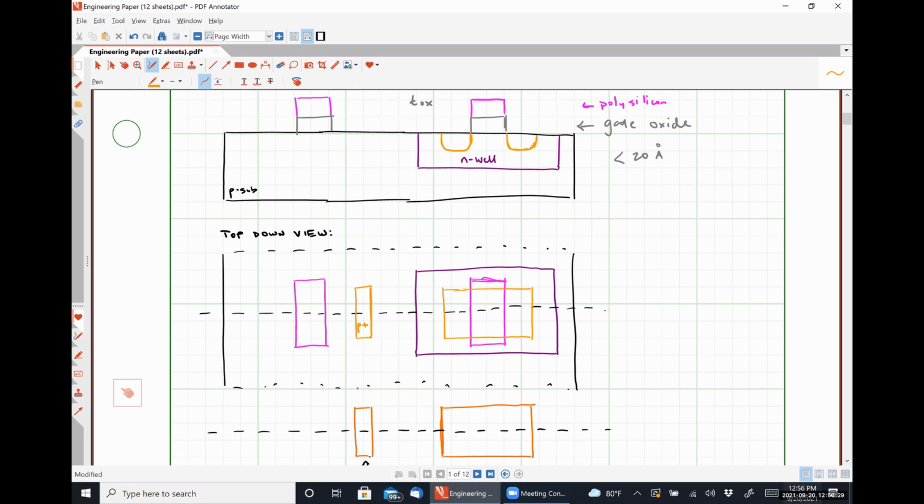is that our source and drain are formed on either side of the polysilicon layer, but our polysilicon layer also gets doped significantly, so much so that its sheet resistance changes from roughly 1,000 ohms per square to like 25 ohms per square. Okay, so it is a huge amount of dopants that are going in there. This is what's called a self-aligned gate fabrication step. So the gate acts as a mask.